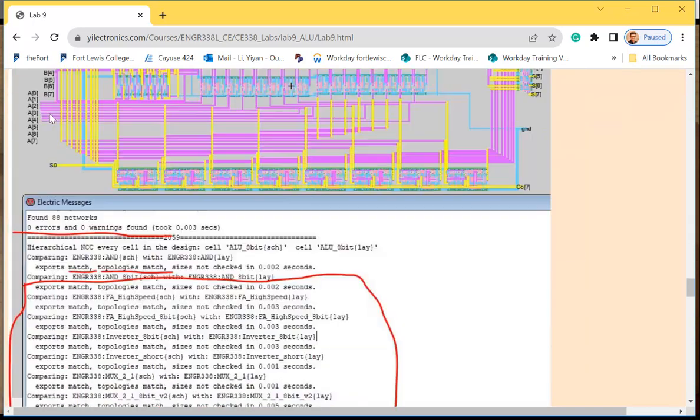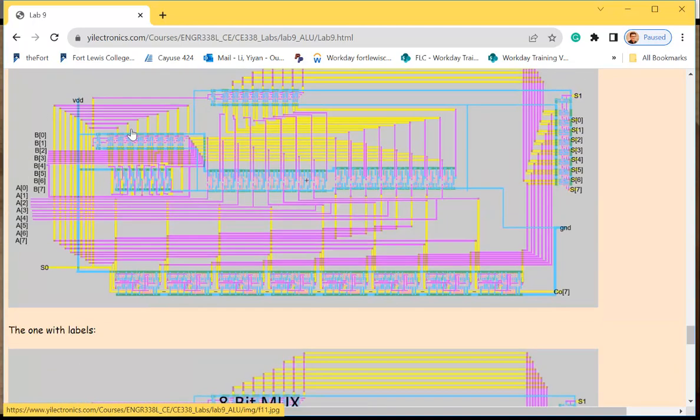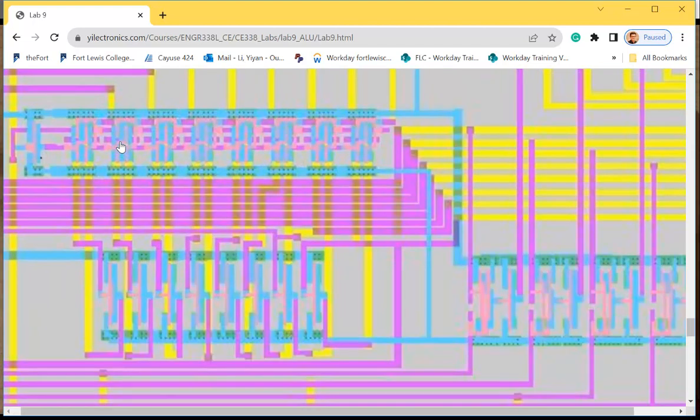So they have different groups of transistors, right? This happens a lot, not just in this kind of slightly larger scale circuit, but in VLSI circuits, where there may be many of these blocks. How do you still do that? I mean, put all the PMOS in the same well. It's impossible, right? How to do that? If you zoom in, you see this is the top rail and the bottom rail.